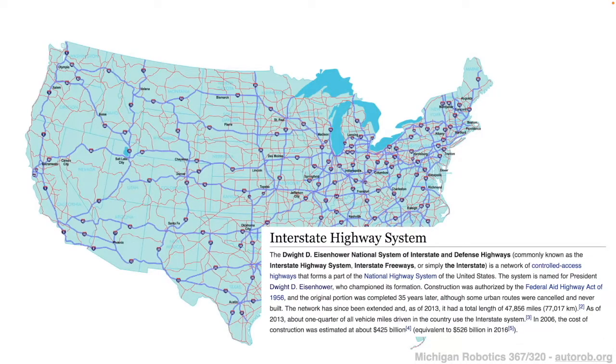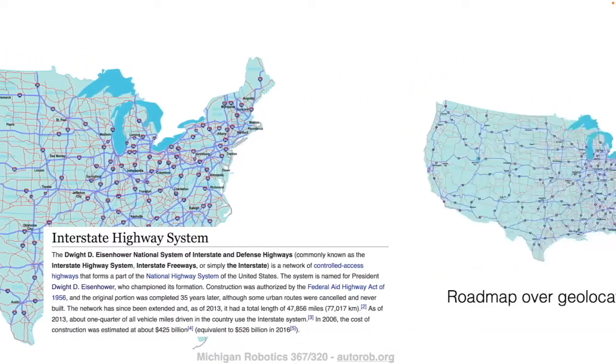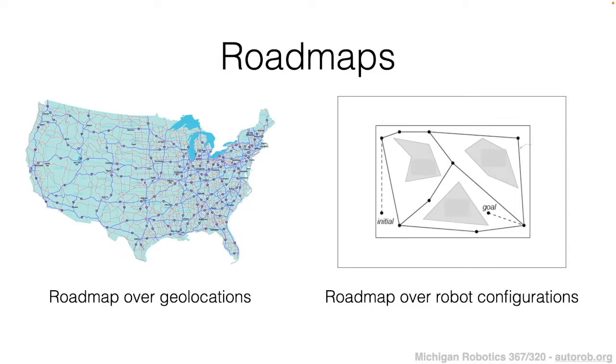the purposes of driving. And in addition to that, it still has the context, because you can relate different portions of the highway system to one another based on, for example, the path length between them, or based on the local frames of reference at a given point within the system. This idea of road maps can be extended from geolocation, from actual road layouts, to robot configuration space, which would extend beyond just autonomous cars, but into mobile manipulator robots or quadcopters and various other robotic platforms.